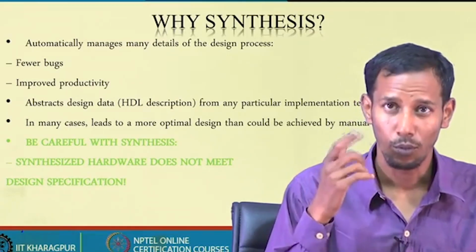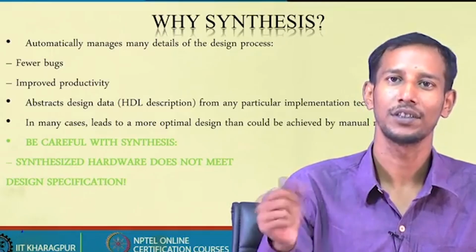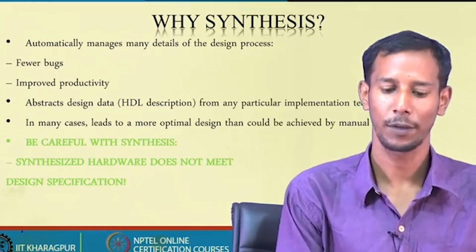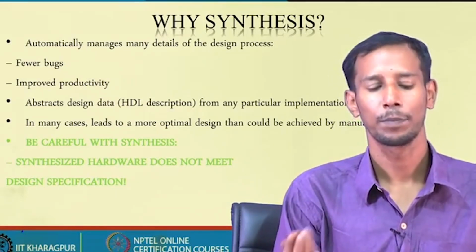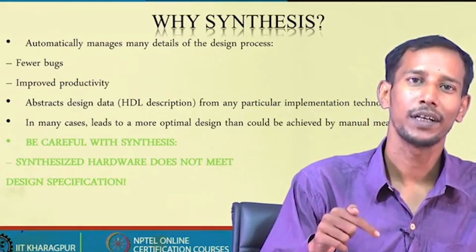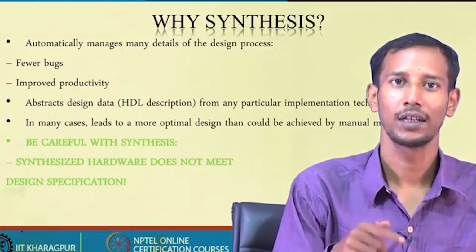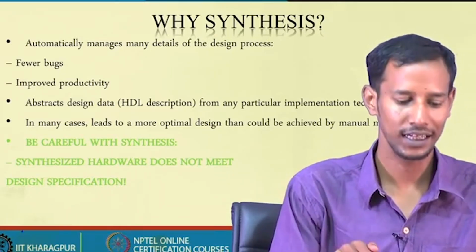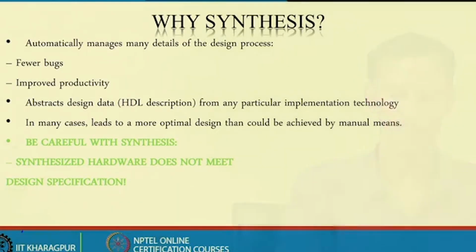Synthesis has to pass through an optimization phase as you are giving constraints to the tool, but in manual optimization sometimes you can make mistakes. So automated tool based synthesis optimization is sometimes better, but whenever you are doing automated synthesis you have to be very careful, because the synthesized hardware may not meet the specification.